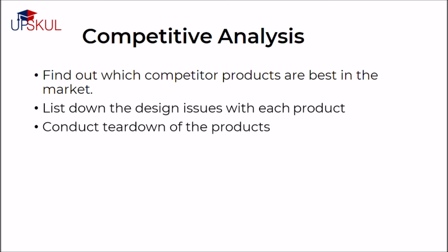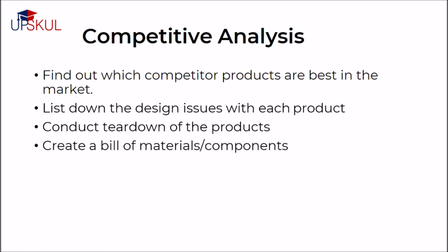Next, conduct the teardown of the product. This is a bit expensive process where you are supposed to buy a product and completely separate all the parts in order to understand the architecture and functionality of the product. Usually, this requires special equipment and a lab. So, if you don't have one, you can also look for solutions online. There are companies that specialize in teardown and provide a complete analysis of the product at a much cheaper price. Next is to create a bill of materials.